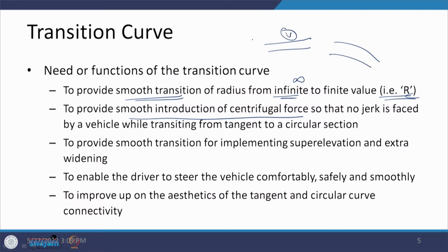Now, when you are coming on this curved section and there is an introduction of P, what we are trying to do is change the value to R c, because you have m v square divided by R c, and this R c is changing from infinite value to a finite value. Slowly and slowly this is happening, and therefore this is a smooth transition, a smooth introduction. So, you do not feel any jerk in this particular case.